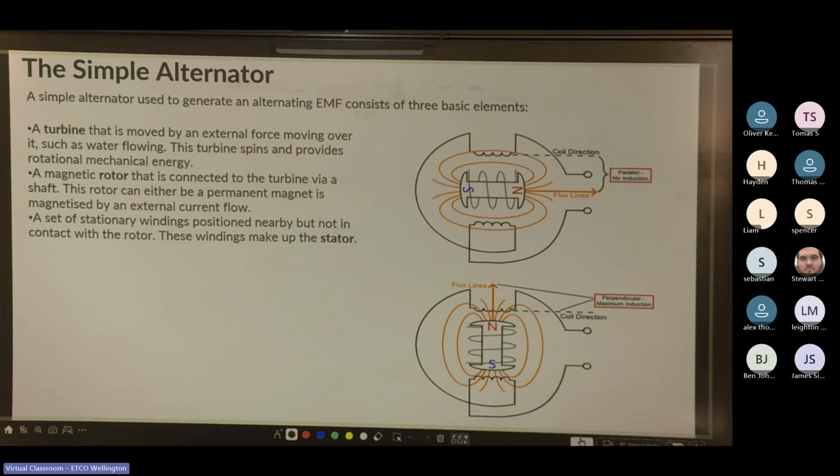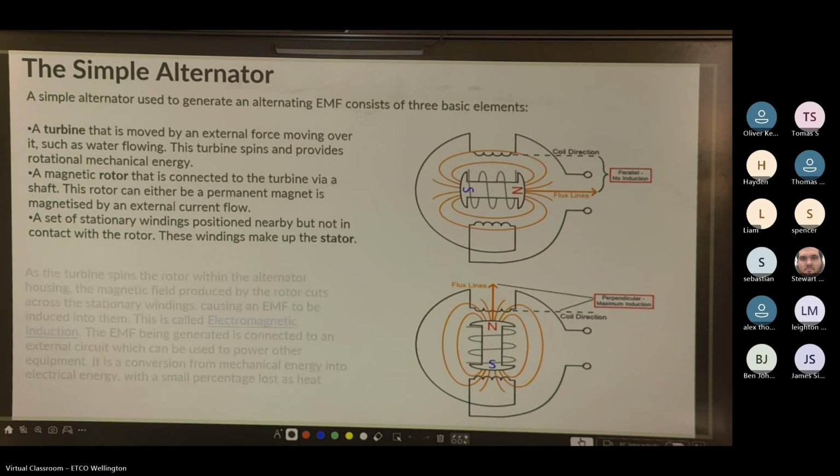So that's the difference between a motor and an alternator we use to generate electricity. With a motor, we use electricity to do work. The windings are made up of varnished copper wire. The varnish is what electrically insulates each winding from the other, but does not block the magnetic field.